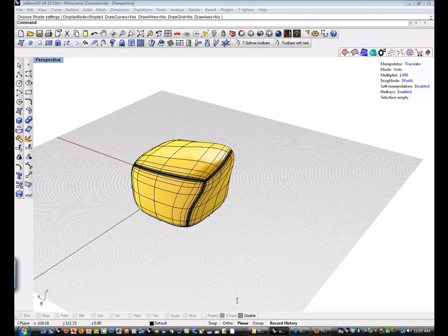Let's see, another question, Kyle. With the convert to NURBS, you can move any geometry while maintaining the T-spline? Booleans are not historically supported. If you take two T-spline objects and Boolean them together, they will convert to NURBS and Boolean together.